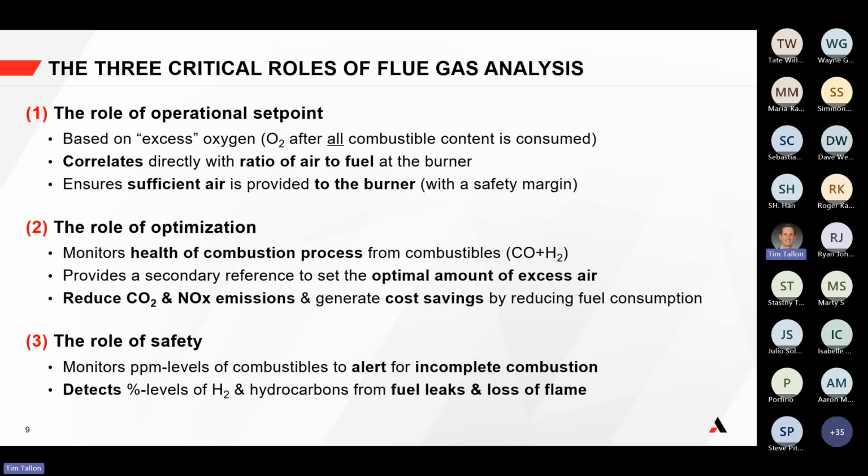So why would an end user look at a flue gas analysis for their process? For one of these three roles or for all of them? For operational set point for quality, for optimization for efficiency, or for the insurance of safety to equipment and to people.